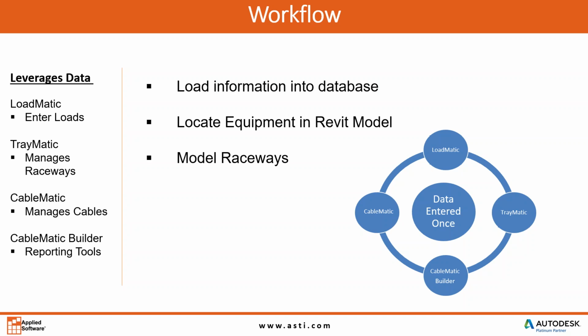Once we locate the equipment, we begin modeling our raceways, using the Traymatic side of the program. Inside of Revit, we can just use the normal conduit and cable tray commands, because it's already got tools built into it.